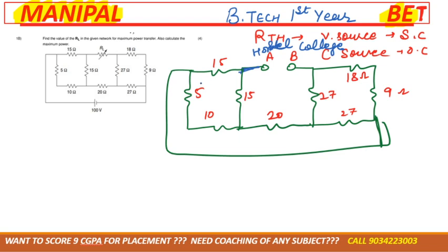Now tell me, if you move like this, are the 5 ohm and 10 ohm on the same path or on different paths? Same path, so we can combine them into a single resistance, that would be 15 ohm. Now in this, no other resistance is the same, because here a wire is there. This wire is connected between the C point, and let us consider the D point.